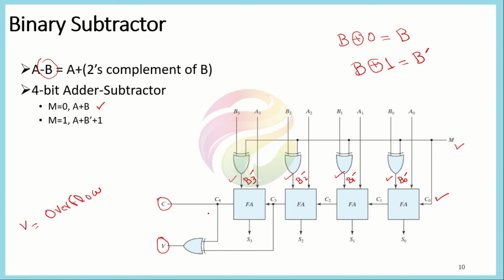But when we are dealing with hardware or digital systems, we need to be very careful about the register size, or how much computation our processor could perform. Say a processor is a 4-bit processor, then it needs to perform the addition within 4 bits. It cannot represent the result in the form of the carry, which generally acts as an extra bit. So if a carry is generated, it means our result has overflowed, or it is representing in more than 4 bits.